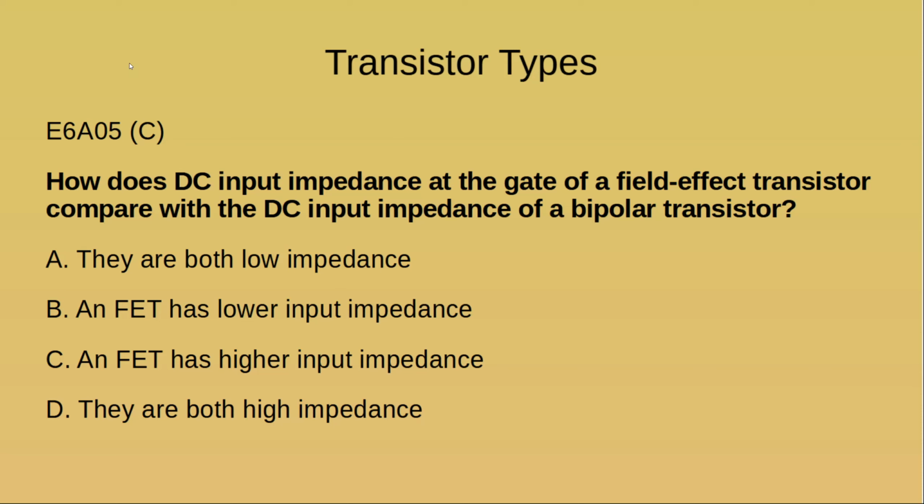It makes a very simple DC power supply, just a resistor, a Zener and a capacitor, as long as you're not drawing a lot of current.